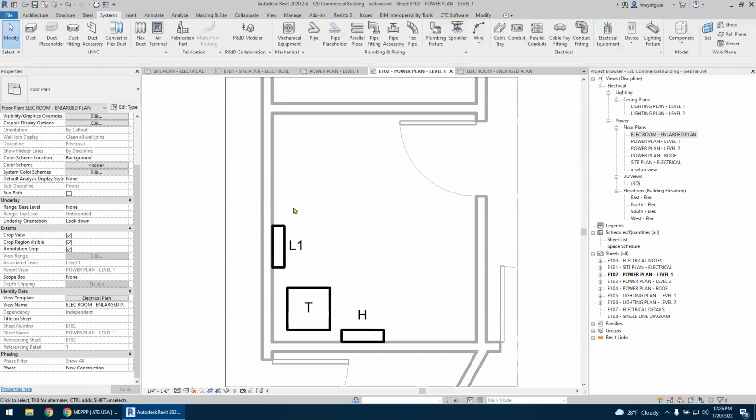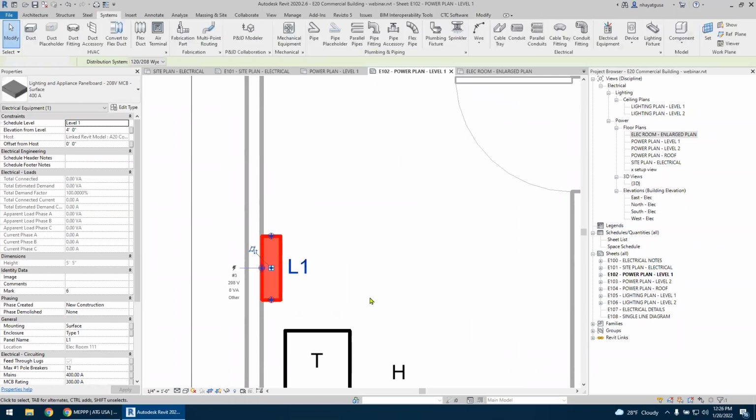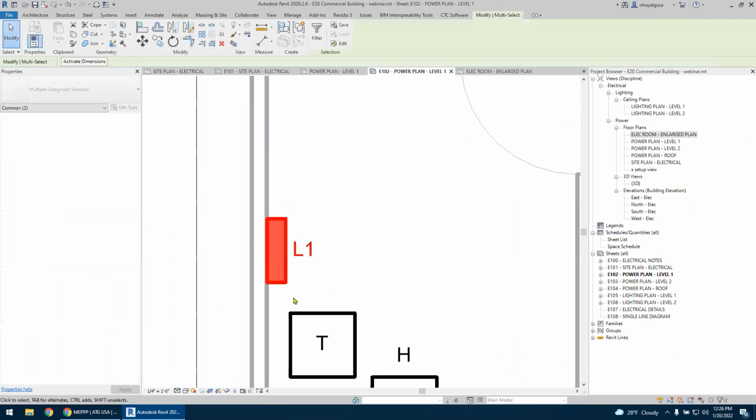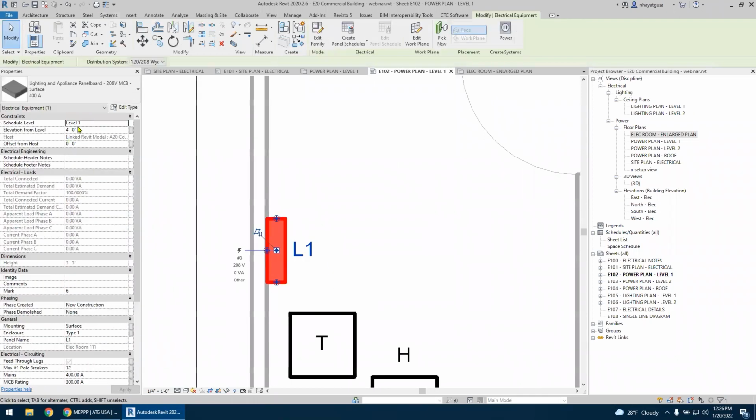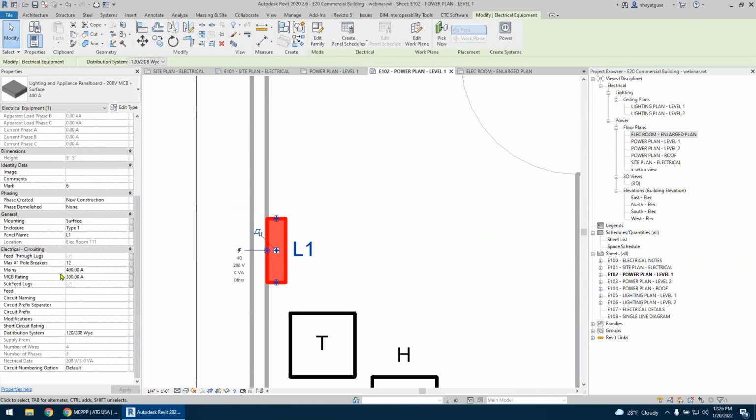Looking good. I need 2 more of those. But before I copy it, let's set it up correctly. Scrolling down. Okay, number of poles, number of breakers. We want a 42 pole slot. None of this really matters. Short circuit rating, we'll go 10K. It's a 120/208Y. The rest of this stuff we can ignore for now. So it's pretty much set up.